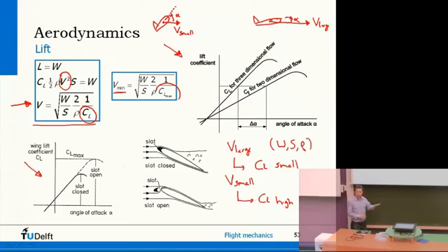Now you know, as you start increasing the angle of attack, then at some point you may have separation. So your lift coefficient will increase with angle of attack, and at some point the lift will suddenly diminish because the flow simply can't follow the profile. So there are different devices that were designed basically to improve this behavior,